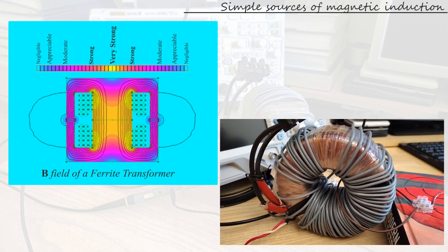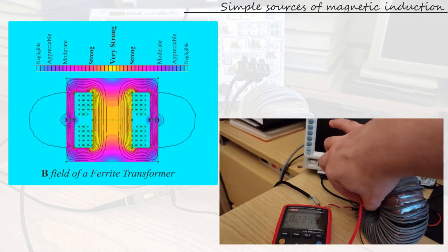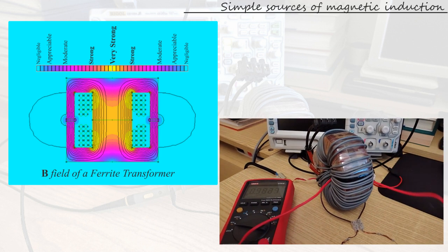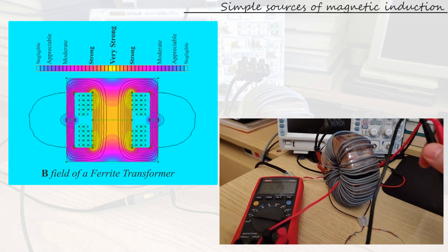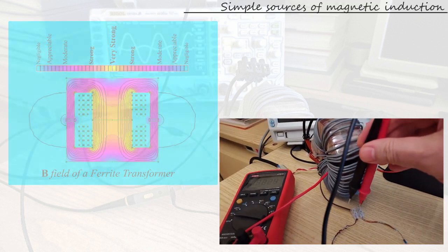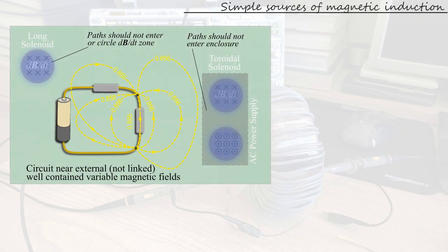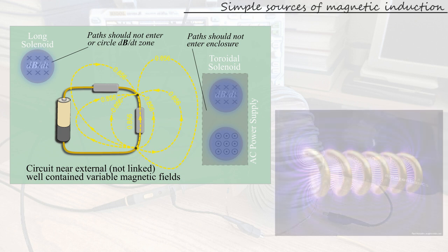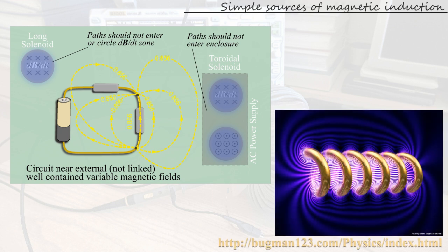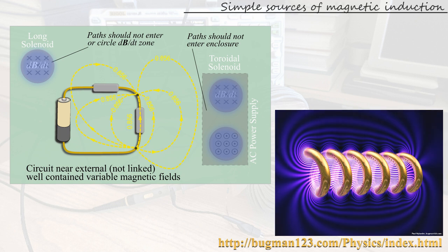In fact, in most cases, all we have to be careful about is to avoid getting inside the magnetic components with other parts of the circuit, or going around them with our measuring probes. I will use the term forbidden zone as a shorthand notation to denote these regions of space. The forbidden zone of an infinitely long cylindrical solenoid is the area that includes the solenoid itself. Ideally, the field is entirely confined inside the coil and extends a bit on the outside depending on how long and how closely wound the solenoid is.